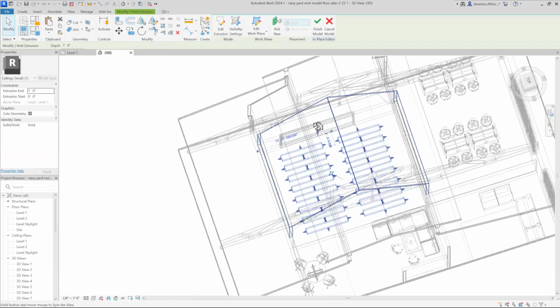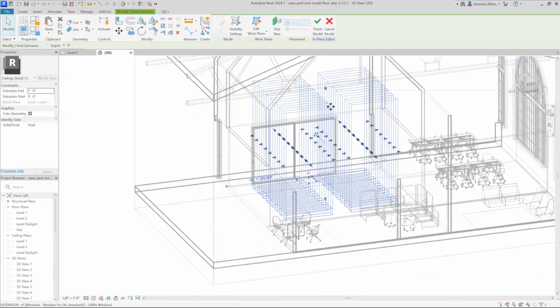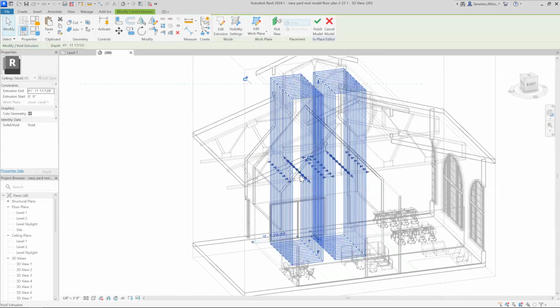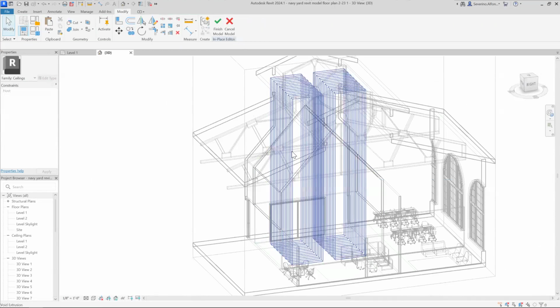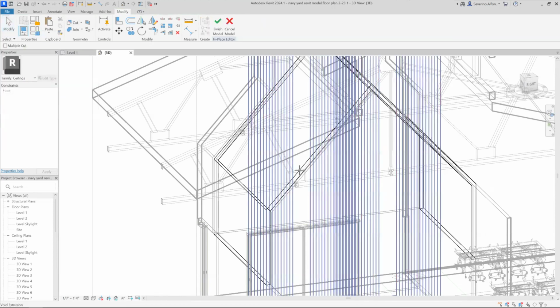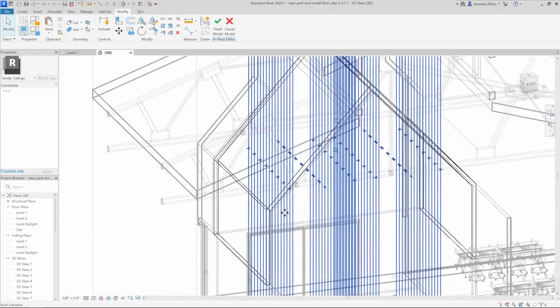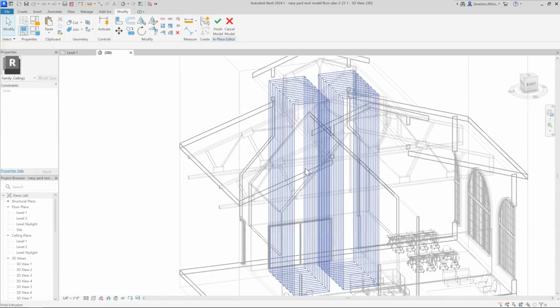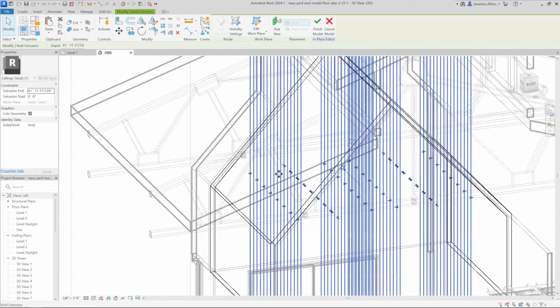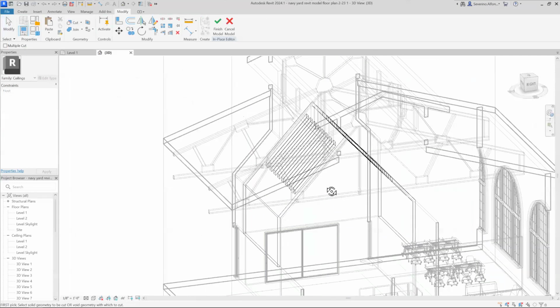You go to 3D, and you don't see much. Even they're like voids, but you can raise those, as much as needed, so they go. Hopefully, they go through that model. Now, sometimes it doesn't do that. There you go. So what I did is, if it doesn't do this, is a void model in orange. Theoretically, it should be cutting through any other model, but it doesn't. So sometimes you have to go to cut, click on the model you want to cut on, and then click on the orange guy. And then you have them there. Okay.